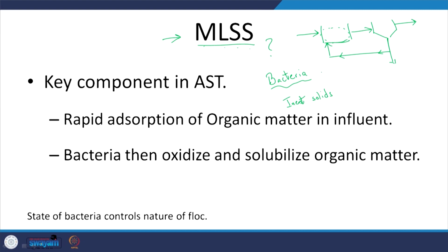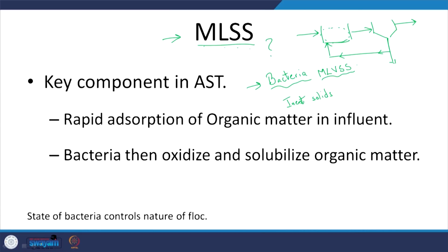So, how do you distinguish between them? Again, these we try to measure as MLVSS, mixed liquor volatile suspended solids. So, you have a furnace, and then increase the temperature, and then look at what is remaining, and that you say is fixed, and what is not remaining, we call that volatile, let us say. So, that is one aspect to keep in mind.